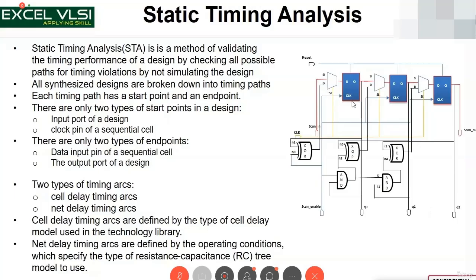If you look at it, any circuit will typically have this kind of combinatorial and sequential path. Now all this you look at, I have mentioned in my own cryptic way. This is one timing arc, let us say input to clock path. Now clock to clock path, another timing arc. Now clock to output path, another timing arc. Now AND gate delay. Now this net delay.